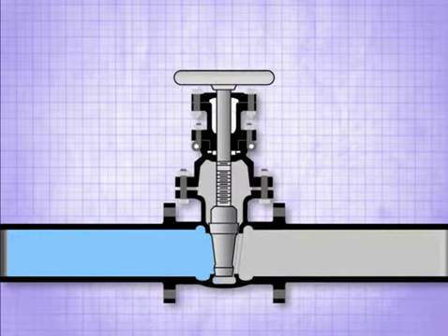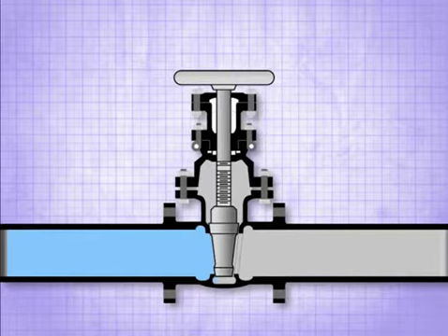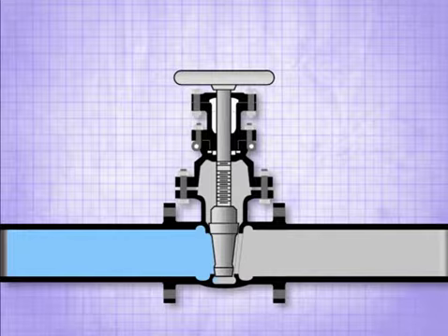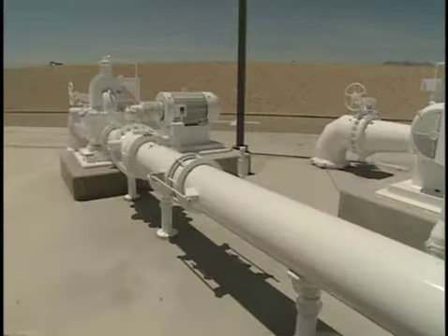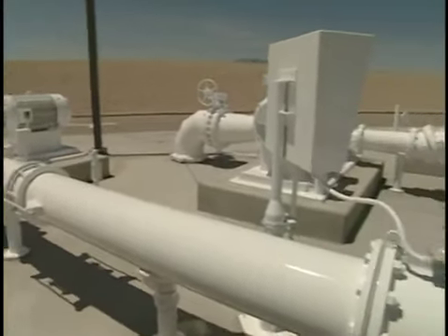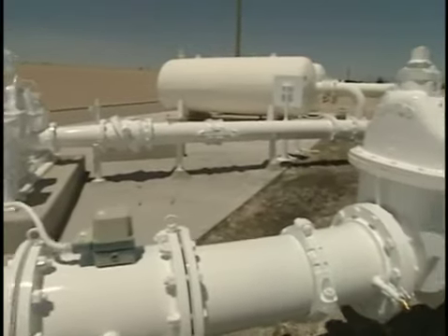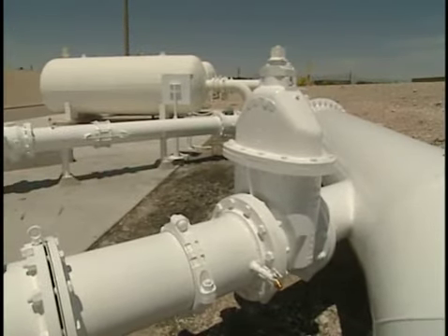The main causes of a gate valve not seating tightly are when the faces become worn or when something lodges underneath the gate. Gate valves should not be used to throttle the flow of water for prolonged periods because vibration of the gates will eventually damage the valve.